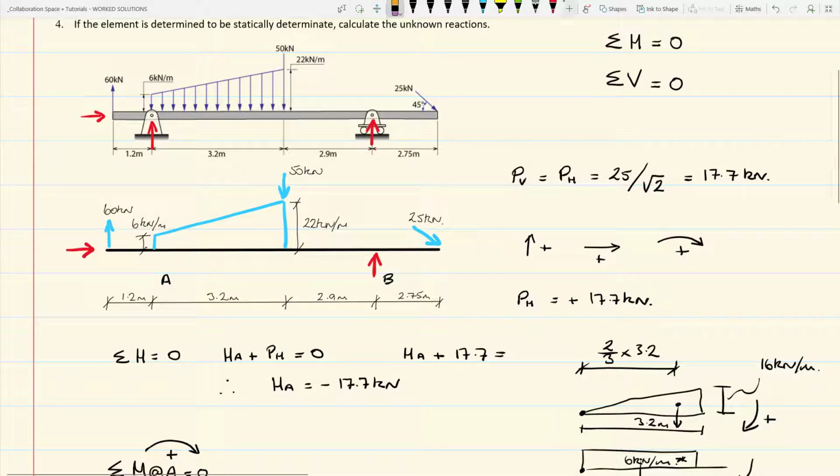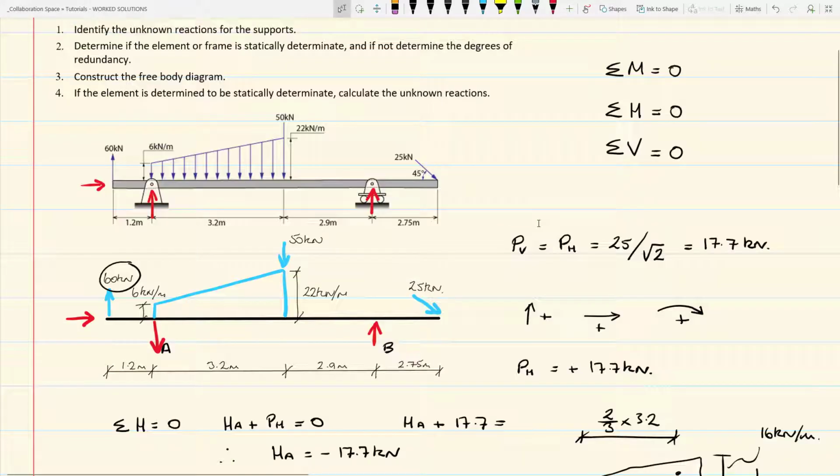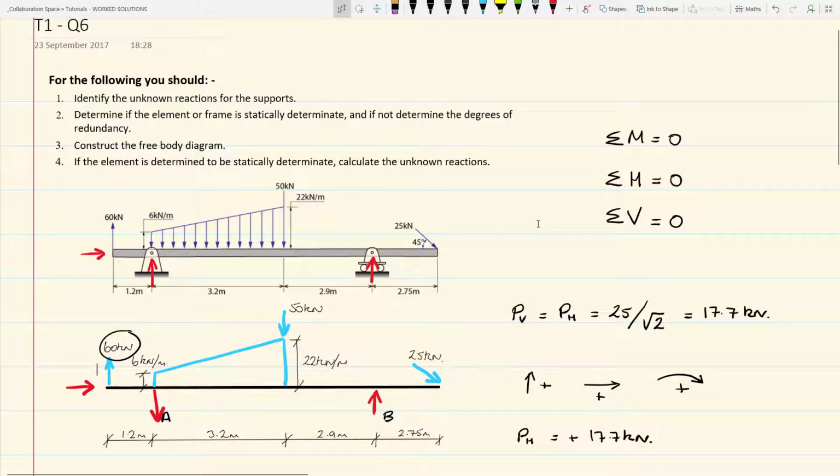And if you look at the magnitude of the loading, again, that makes sense. So we have a vertical force holding the beam down effectively. And if we consider the magnitude of the loading, you have 60 kilonewtons here on the end of the beam. That is effectively trying to lift the beam. So in order to oppose that, it would make sense that we have a vertical force acting down, trying to hold the beam down. This problem is now complete, as we have resolved the vertical and horizontal reactions associated with the pin at A and the roller at B.